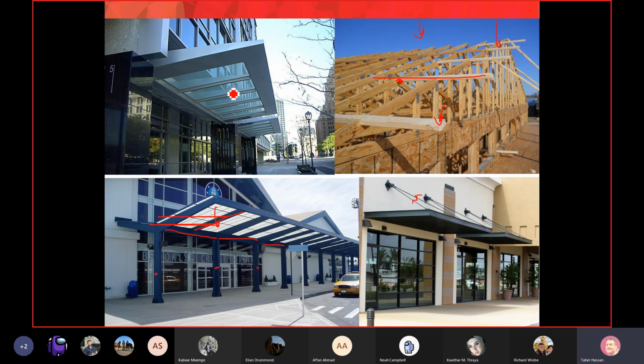And I will say the same thing here. The top left picture, we also have a canopy, and there are no cables and no columns. So the only way for this canopy to stay in place is to cause torsion. We have a beam here, and if I apply gravity load here, it will simply cause this kind of bending moment around the axis of the beam, a twisting moment.